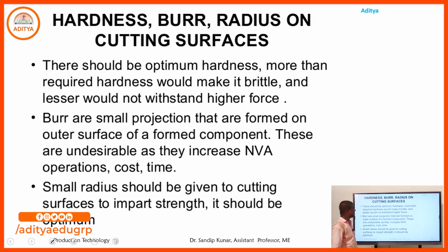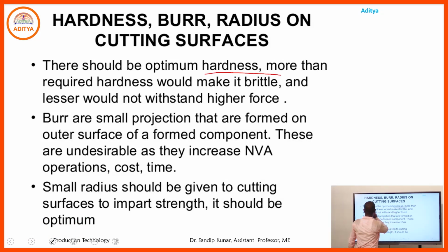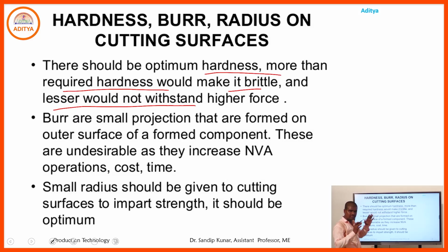Hardness, burr, radius on cutting surfaces. Sometimes optimum hardness is needed; more than the required hardness would make the material brittle. If we take more hardness in that particular material, the material will be brittle, and lesser hardness, a lesser hard material, will not withstand the higher force.